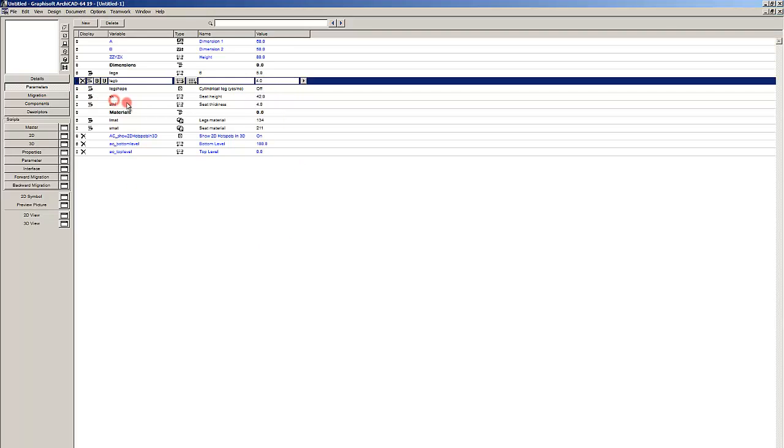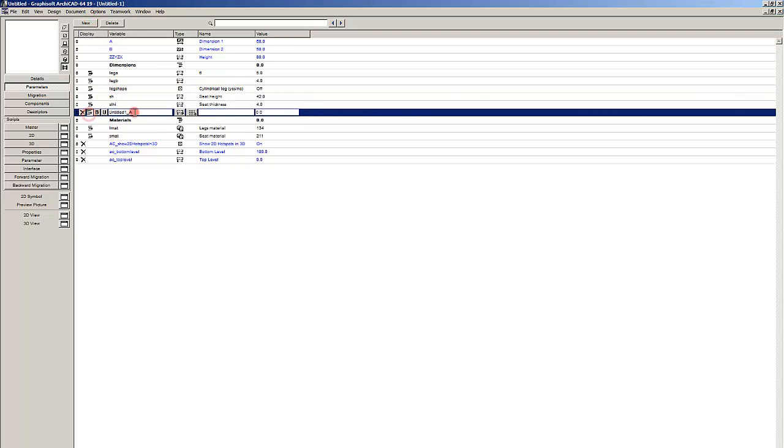First we will create the first leg, and we will type another as off, which will be seat offset around legs, and that means the seat will be overlapping the legs from this value. It cannot exceed, of course, certain limits, but for the sake of this exercise I will type 5 centimeters.